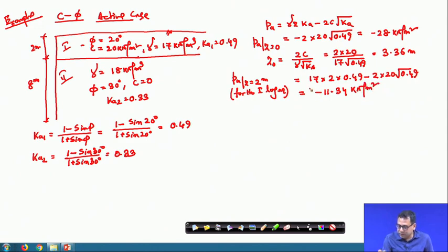It is still minus because your Z0 value is 3.36 and your thickness of this layer is 2 meter. So, this layer totally will be under the negative stress. If this layer thickness is greater than the Z0 value, then there will be a positive stress, otherwise it will be negative stress.